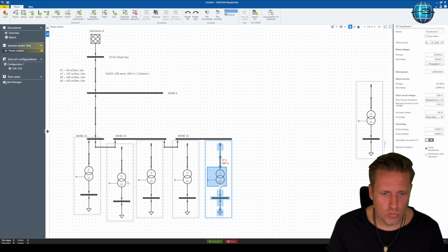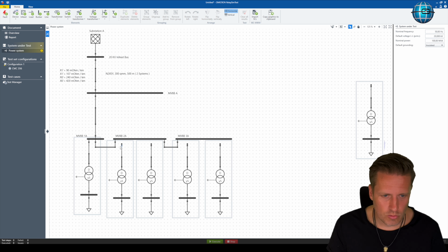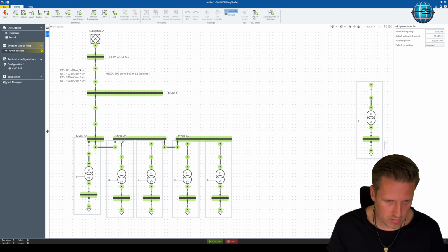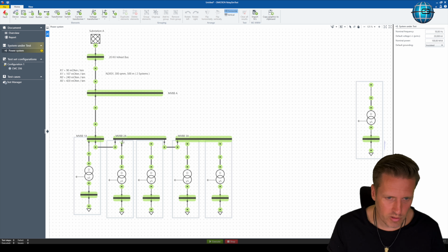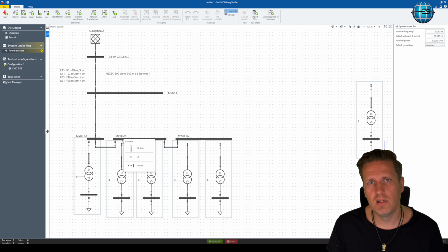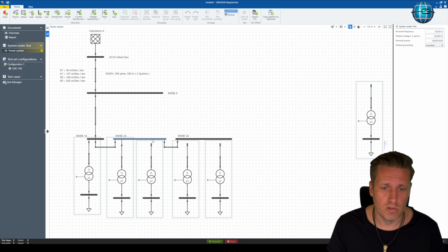and all we have to do now is to connect them, and for that we just take this wire, put it to the top, and the software now asks us if we want another CB line combination, if we want to add another circuit breaker, or if we just say no, I have enough circuit breakers in my grid, just merge it, and it will merge it.